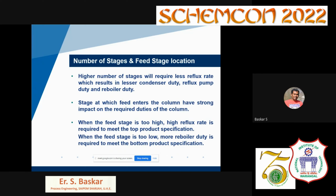And also the stage at which the feed enters the column. The feed can enter at any stage of the column, but the location where it enters also has a strong impact on the duty of the column. When the feed stage is too high, for example, when the feed is entering very near to the top of the column, then high reflux rate is required to meet the top product specification, because the composition of the feed will not be equivalent to the top product that we are going to get from the column.